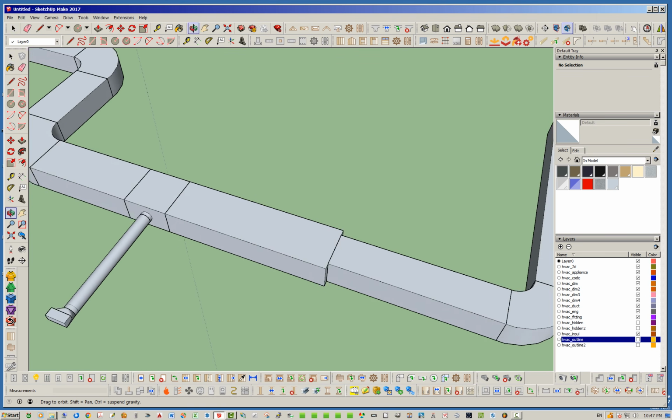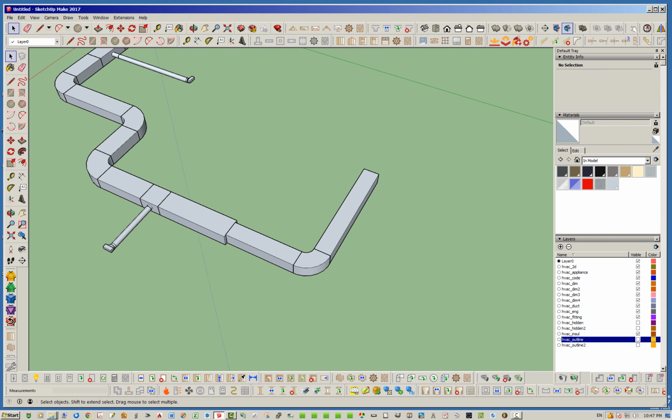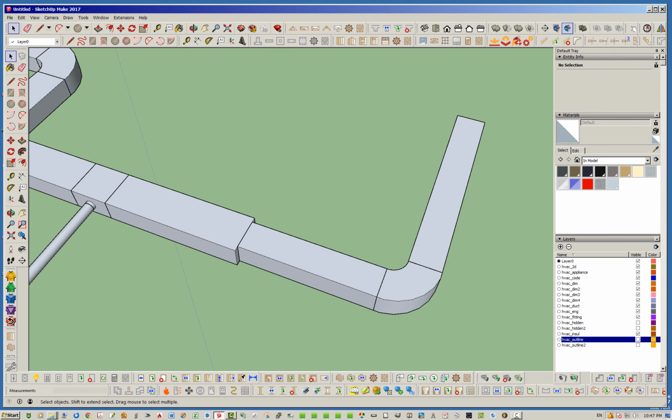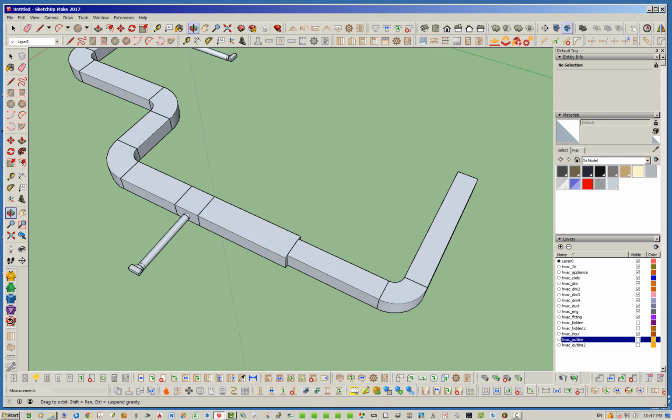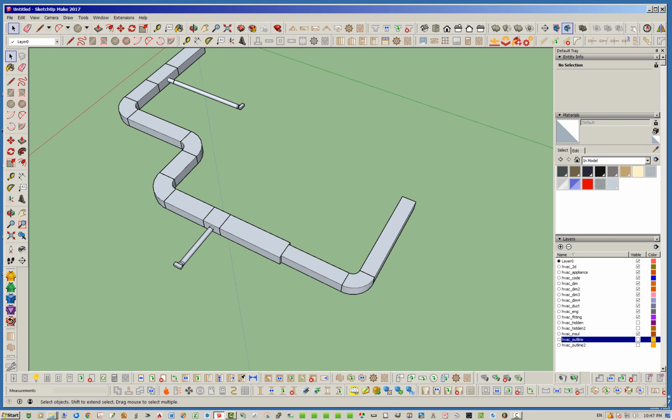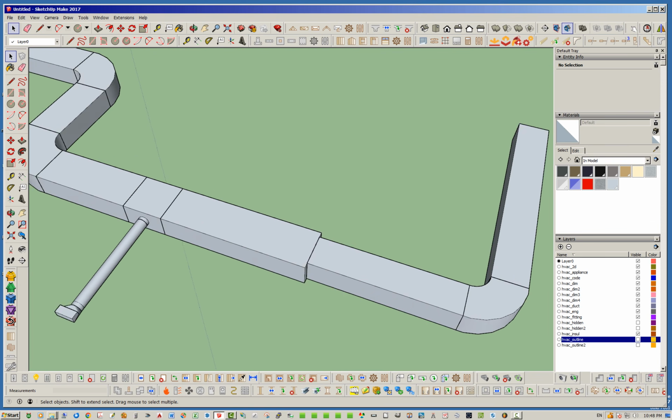Okay, so right here, I'm going from a large trunk line and I'm necking down to this 18-inch trunk line, right? So I want to add a transition in there. And so that's what I was meaning by transition. So basically, for the main trunk lines, we have bends where you have 2 edges coming together. We have a T where you have 3 edges coming together at a single node. And then we have a transition where we basically have 2 edges coming together, and it's not a bend, it's just simply a transition. And so it's a little bit different.